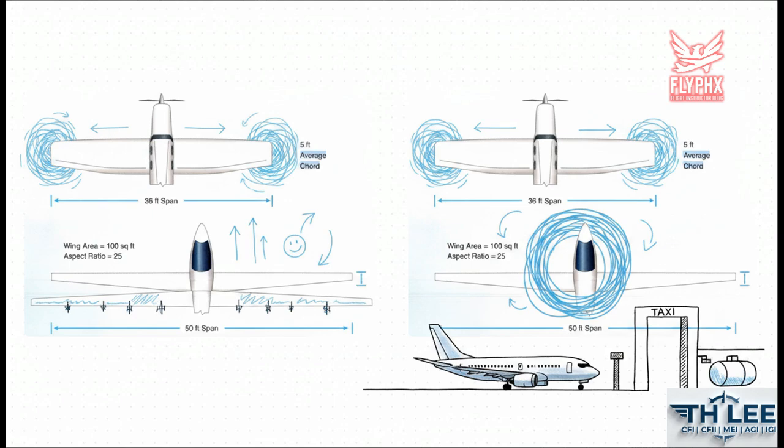3 main reasons. First, structural integrity. Just like extending a long tape measure, a long wing bends really easily and requires heavy structural reinforcement. Second is maneuverability. Long wings have a high moment of inertia, which absolutely kills your roll rate. And third, practicality. Try fitting retractable landing gear, massive fuel tanks, and taxiing a 200-foot wingspan into a standard airport gate. It's just not going to happen.